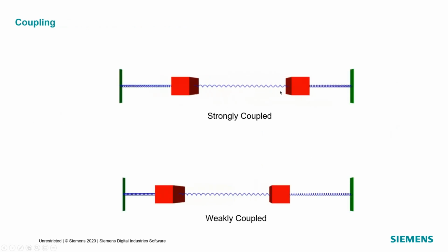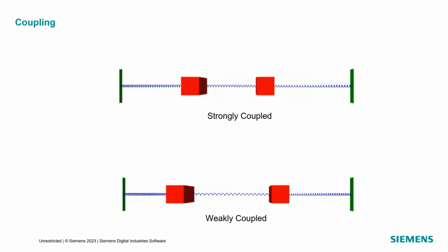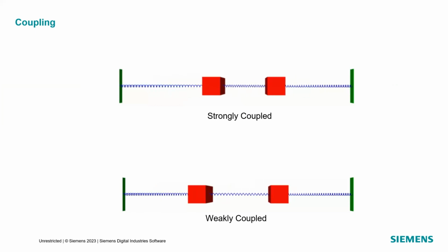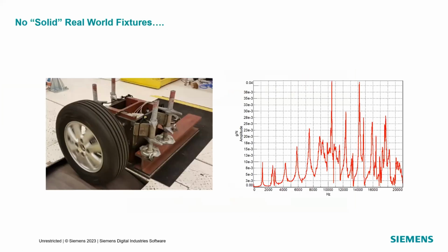If you have a strongly coupled system that interacts a lot, the force estimate would be off, not for troubleshooting or understanding what's going on, but off as far as what we would call a blocked force, which is a force that's independent of the supporting structure.